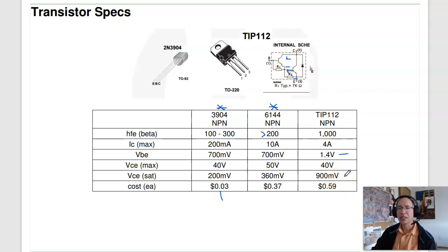The reason they have a Darlington pair is it's kind of hard to build a transistor that can handle high currents and have high gains. So what they do is they use two transistors. The second one has a high current capability and a gain of like 10. The first one is a higher gain and lower current capability. Put the two together, I have a high overall gain, 1000, and high current capability. But the cost is it loses 1.4 volts across it, and I can't saturate it.